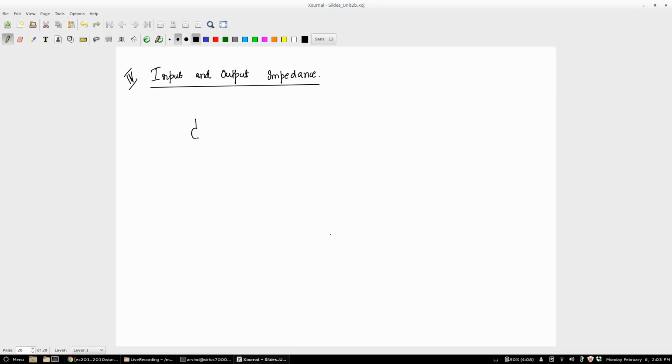So, if I draw the incremental circuit, what do I have in the incremental circuit? I have a small signal source, so this is Vs, I have RS, then what do I have? I have my RA parallel RB, correct? Then that goes there. Similarly, on the outside I have a current source. The current source value is gm VGS, this plus minus is VGS, correct?